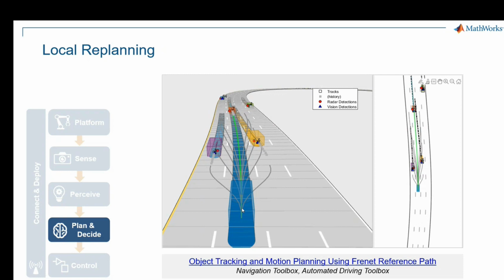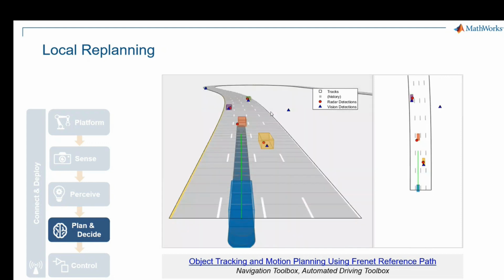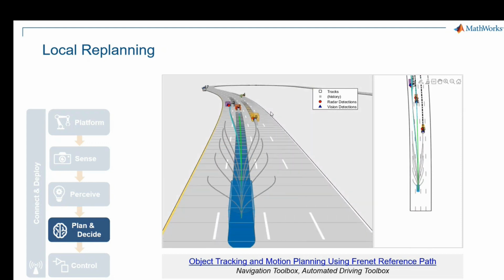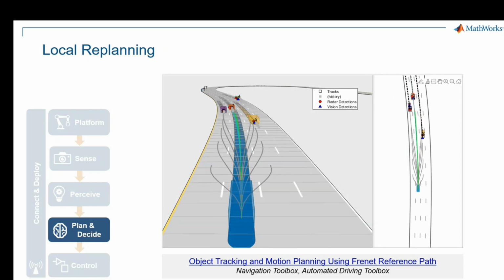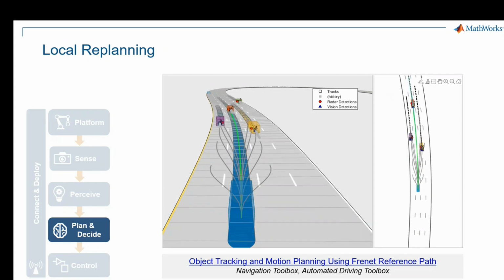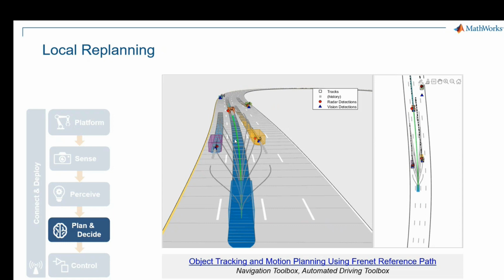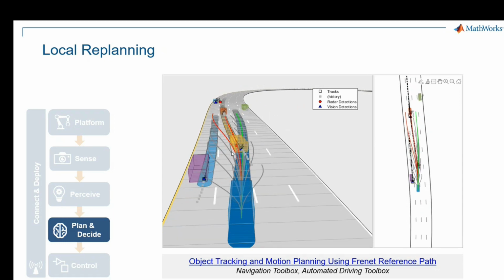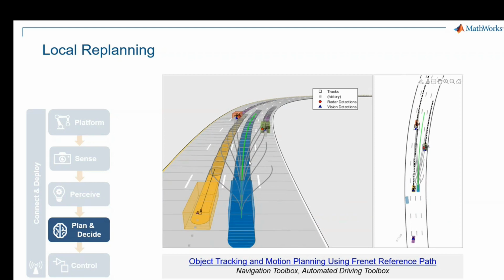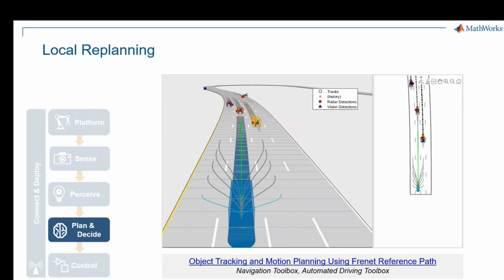a list of alternative trajectories, the ones in gray, and by using the list of obstacles, it's going to modify the trajectory to an alternative one or not. And it's also going to have logic to move between just keeping the lane, changing lanes, or vehicle following maneuvers. It's all based on the cost and whether it's a collision-free motion or not.